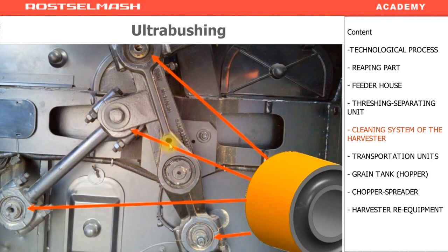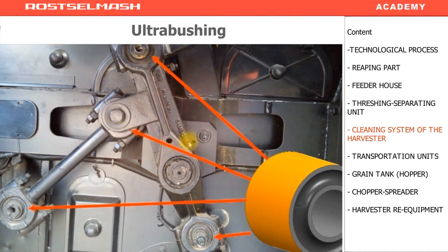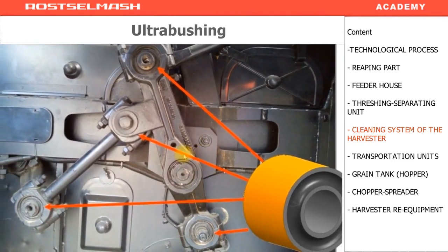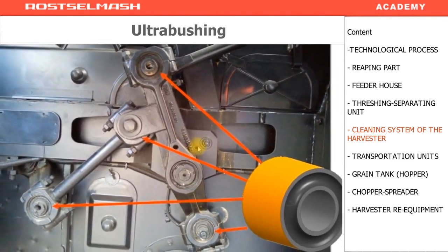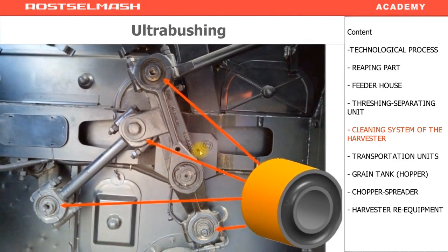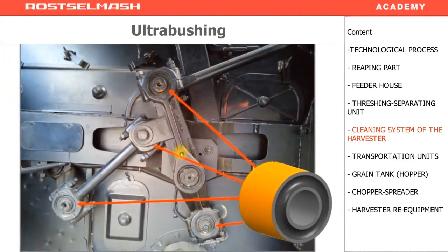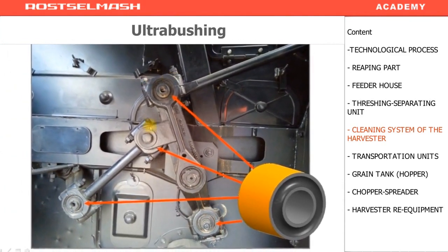In any case, we won't be able to push the lever to this hole. That's why we can only align it with one of the holes, the one which is closer to the cab. Why are there two of them? These parts are uniformed. So on the other side, there is an identical one with another hole. Insert some kind of a pin here, and then you can press the covers.